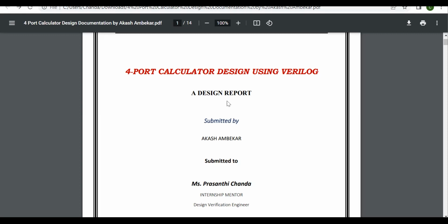Baud rate is nothing but a replacement for the clock. In UART you are not using the clock for synchronization, so for that purpose we use the baud rate. We have seen baud rate calculations and how to generate the clock using baud rate in the code also. So once again go through that project details. I have shared the specification, code, everything with you.